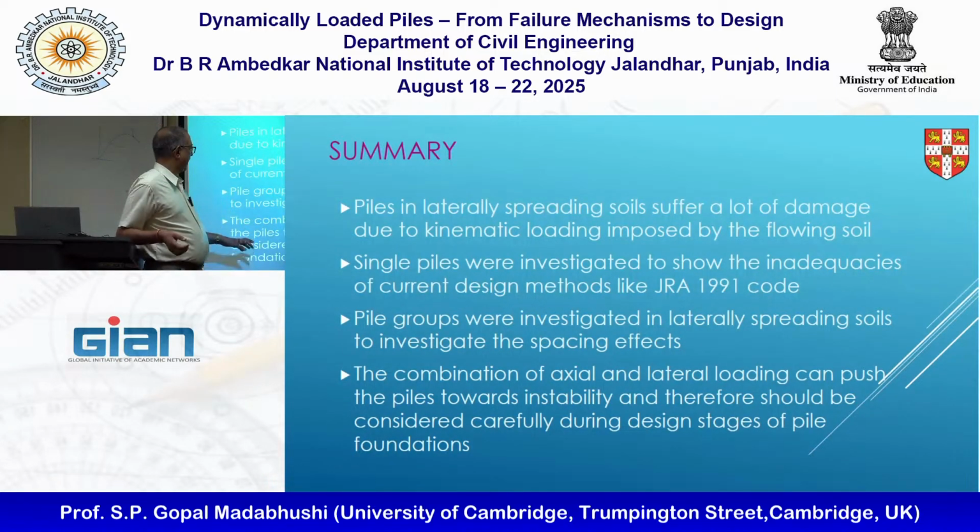So you need to consider the combination of axial and lateral load, and that obviously can push the piles either towards instability in one case, or if you design them more carefully, towards stable yielding. And obviously my design recommendation will be try and design your piles to suffer more stable yielding, which is always a safe design. Unstable collapse never is. Okay, right.